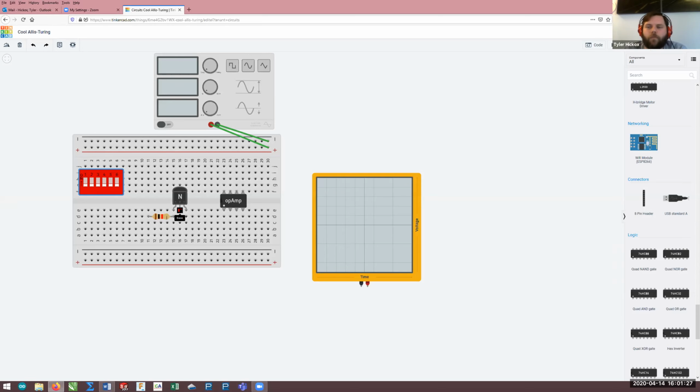So our circuits labs usually contain 5 to 6 different parts. Sometimes it'll be an inverting amplifier or a non-inverting amplifier. So we will share a basic circuit with them and then say, change these values so you get a gain of 2, or change them so you get a gain of 5. And that way they know their limit.